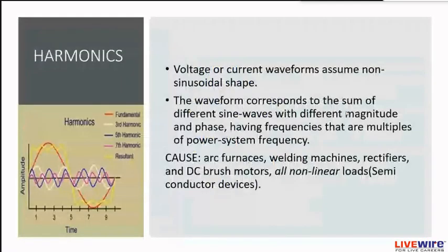First, we talk about the harmonics. So what does harmonics mean? Any deviation from a perfect sine wave can be represented by the harmonics. We can describe the harmonics as multiple sinusoidal components having a frequency that is an integral multiple of the fundamental frequency; that we call the harmonics.